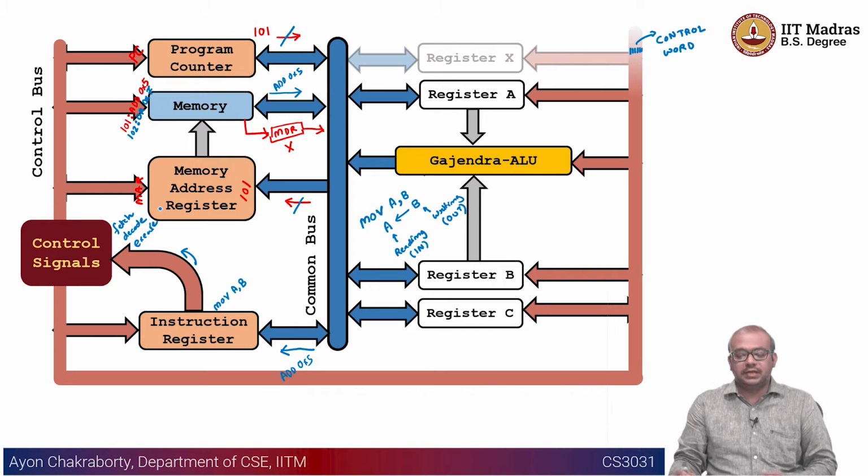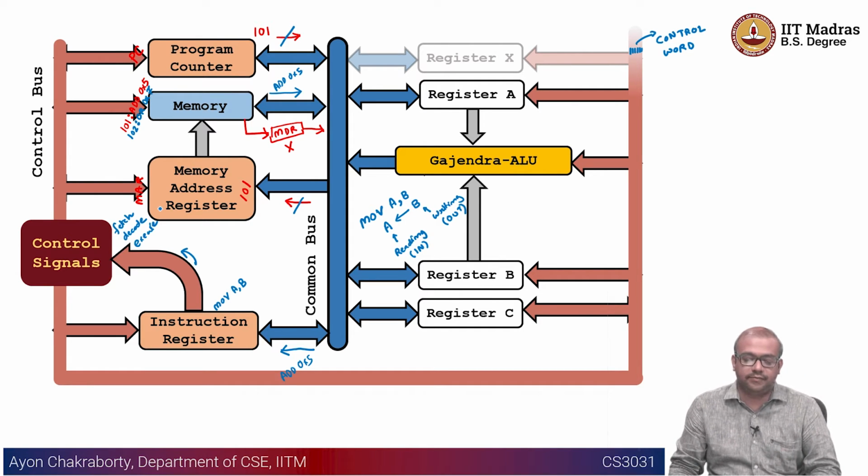So execution is the last phase where you really execute the instruction. Fetching and decoding are a part of the instruction execution, but not really the execution. The execute part does the job, right? Which is typically, I would say, simpler, right? Execution is going to be some combinational circuit operation in the ALU.